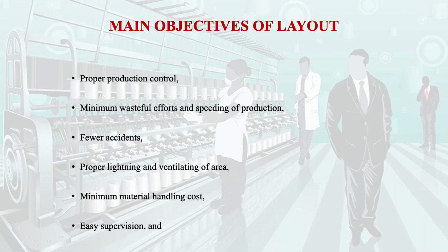You will find, if you visit a factory, that there are instances where the distance between two successive or sequential workstations is very far. It means one station is away from the second station, and there is time involved in the material handling, so there is a cost involved in the material handling.